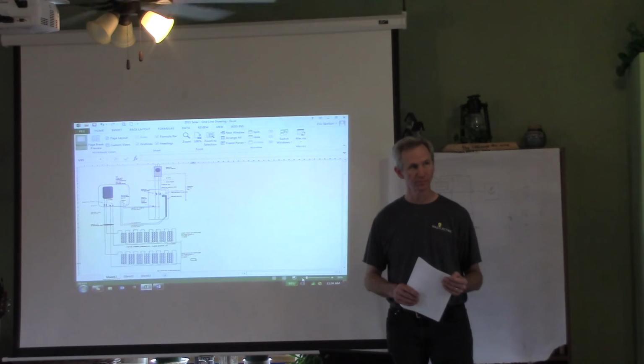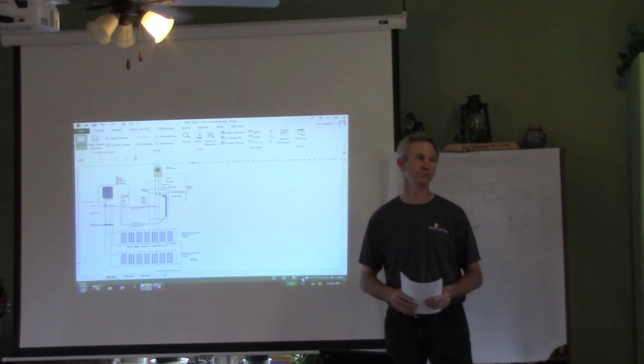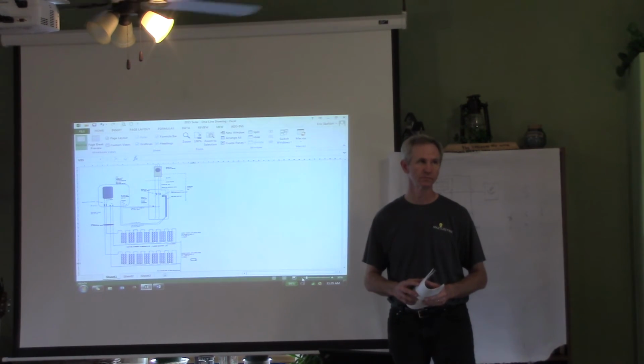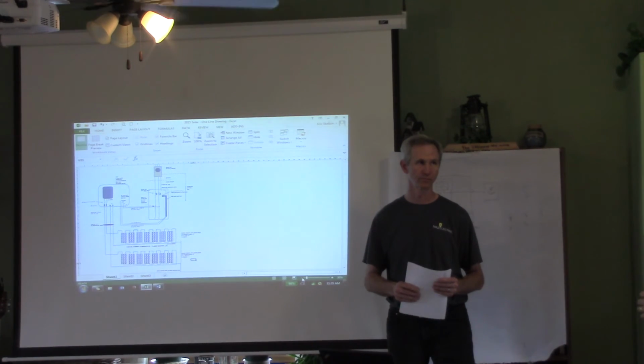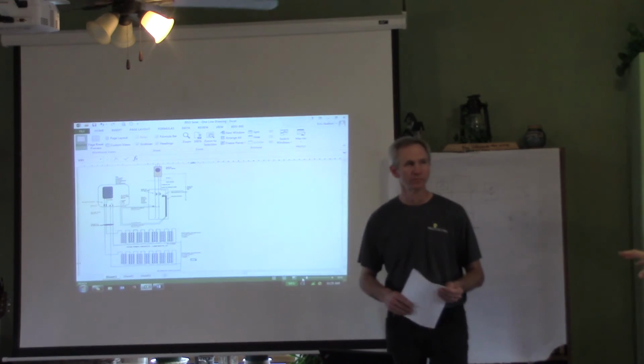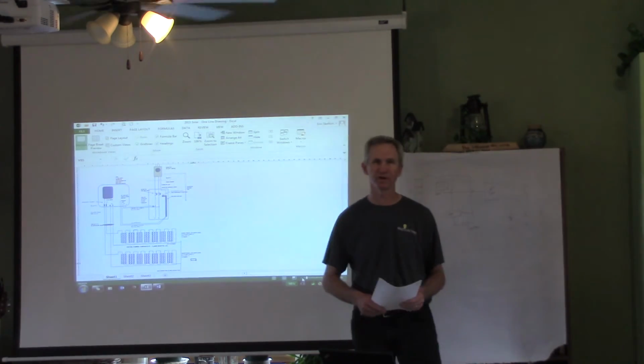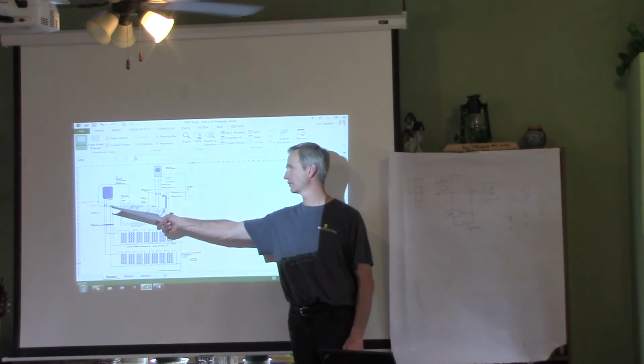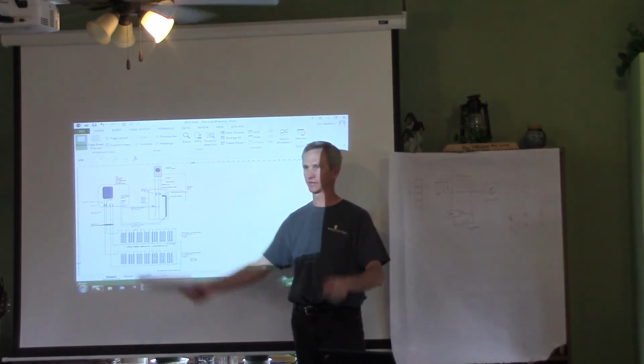Don't want islanding to happen, meaning independent power production without the utility is unsafe, because they can reclose those wires out of phase or hurt themselves. So my point is that the utility company themselves has guidelines they need to stay within. It's typically 15% of the capacity of the line size going to a particular area where there's a power plant. If it exceeds that, then they have to put monitoring equipment back on their equipment so that they know that you're on before they work. So there's technical reasons why they want to give you permission. And again, it's simplified for us in this: a UL listed inverter device, which immediately shuts down if power is not sensed on the system.